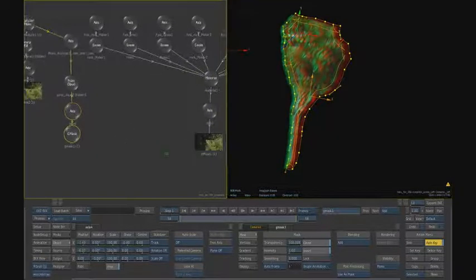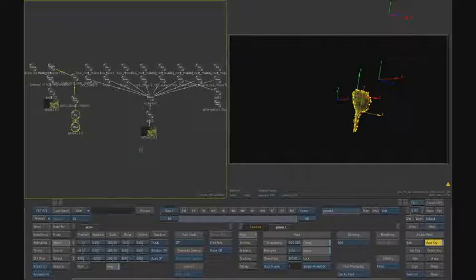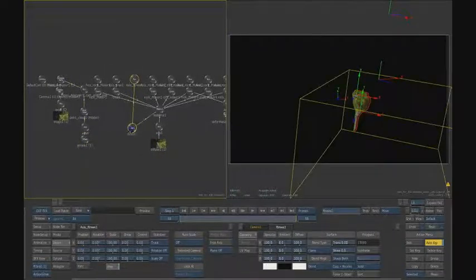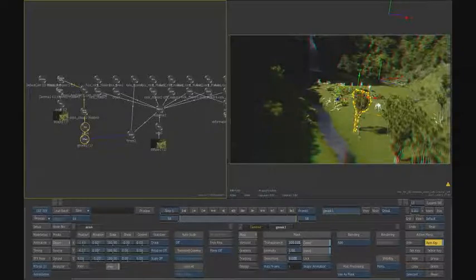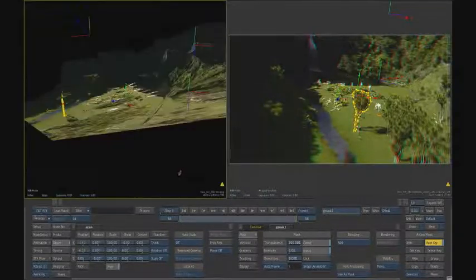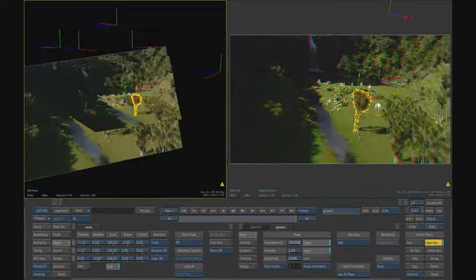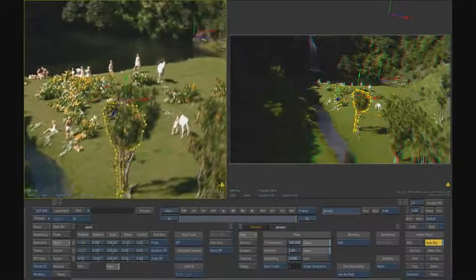The next thing to do, of course, is to make our mask, instead of cut the entire environment here, we want our mask to cut just the geometry that we care about. So it's a selective mask at this point. When I go like this and have it cut just that tree, leaving the rest of the objects uncut. So it looks a little like this from a perspective view. What's happening is the mask is refining the edges of my geometry.